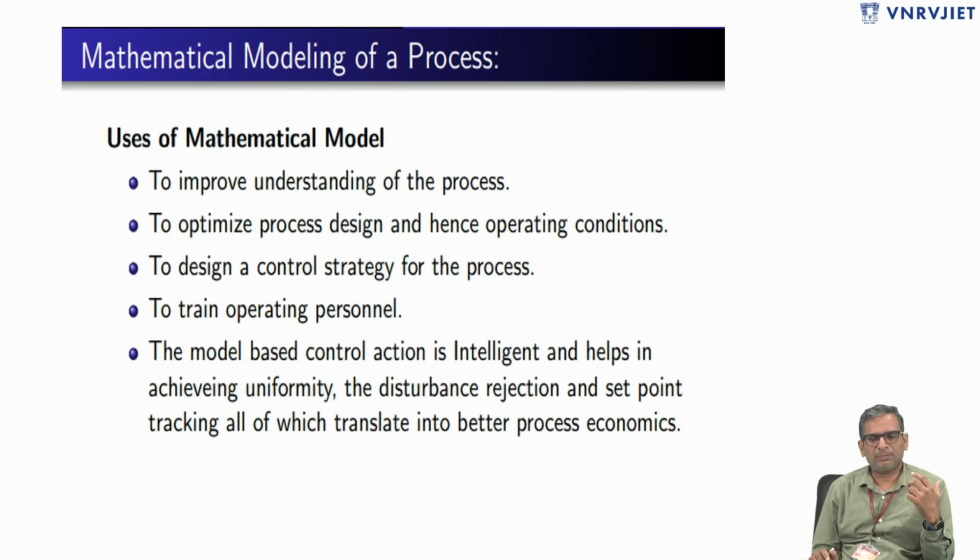So once we have a plant, once we understand the nature of the plant, say whether it is linear or non-linear, once we have a model, we can relate input with output and other plant parameters. So we can use it to design a control strategy. So whether I should go with a P controller or PID, right?